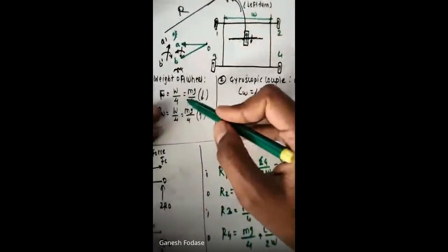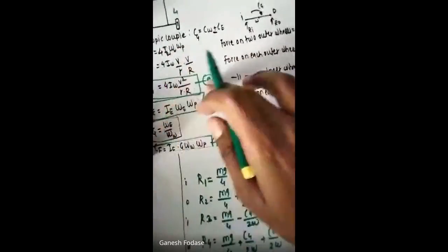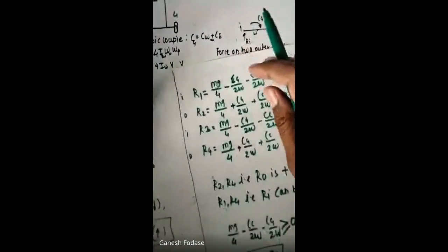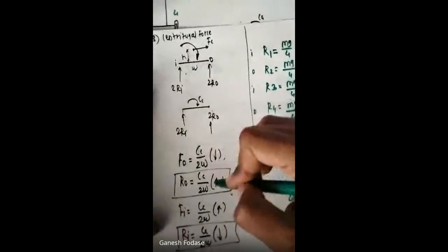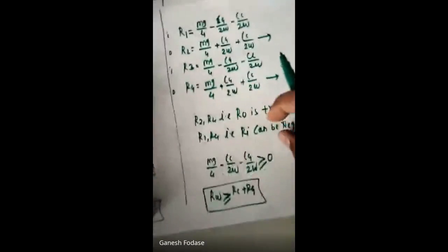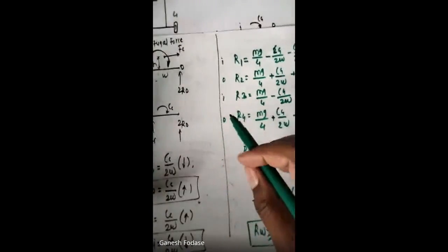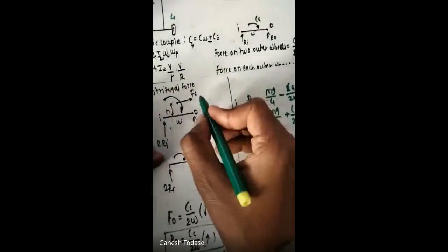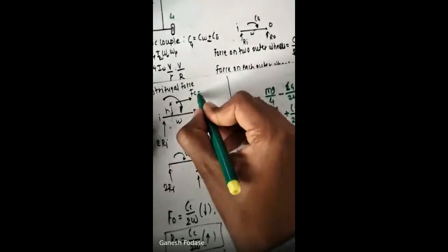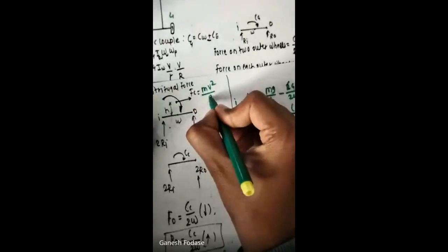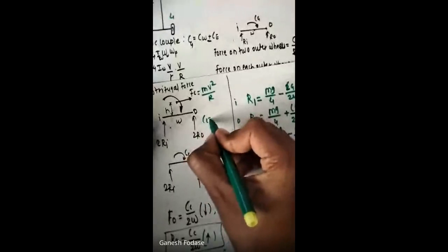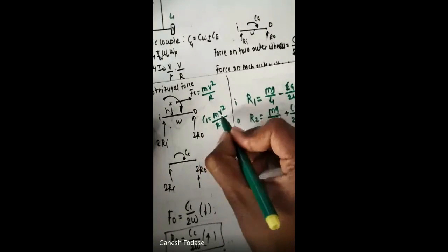Solve in the same procedure, means find out these reactions due to weight, couple due to wheels and engine, depending on plus or minus. Then find out couple due to centrifugal force, add this, use this condition. Now once you put here, Cc is nothing but centrifugal force Fc into H, and Fc is nothing but mv square upon r. So Cc is mv square by r into H. And Cg is already known to us.